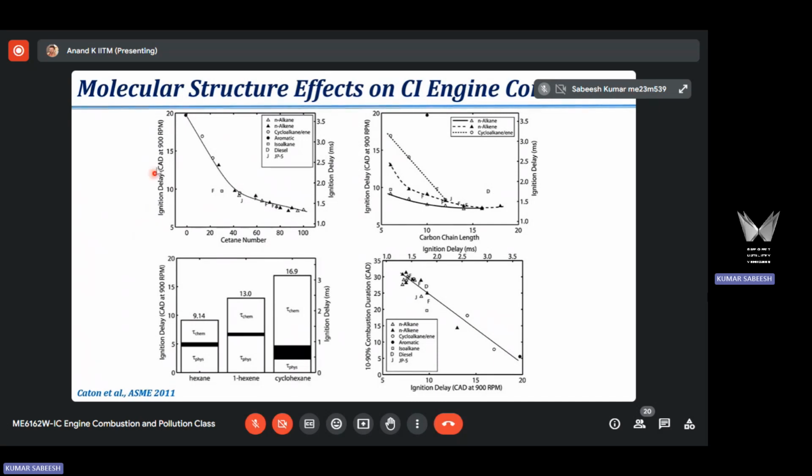So technically, there's nothing called a delay time. And technically, you cannot relate the combustion effect on the delay time for SI engine. That is a direct answer to your question. The delay time that we define for SI engine is based on how much time is required to form a stable flame. There is no delay for ignition, but there is some delay to form a stable flame. That time is sometimes encountered as ignition lag or delay time in SI engine.